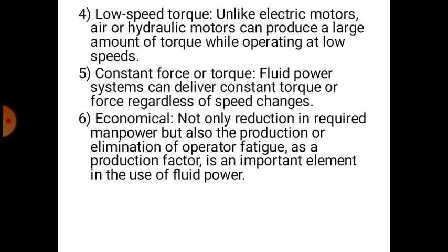Low speed torque. Unlike electric motors, air or hydraulic motors can produce a large amount of torque while operating at low speeds. So at low speeds also we are going to get high power and constant torque. A fluid power system can deliver constant torque or force regardless of speed changes.